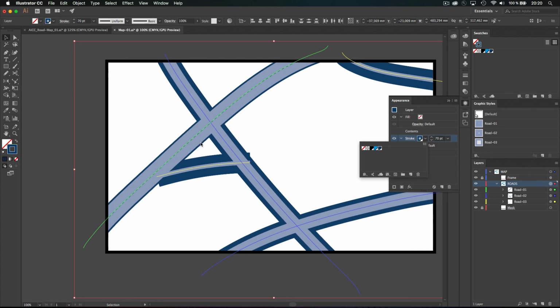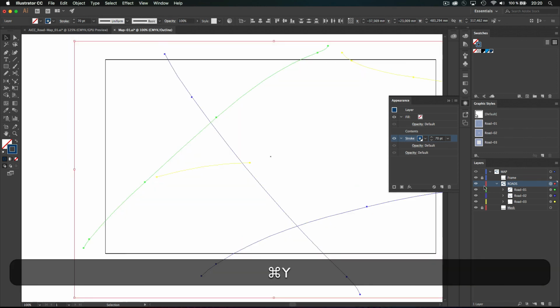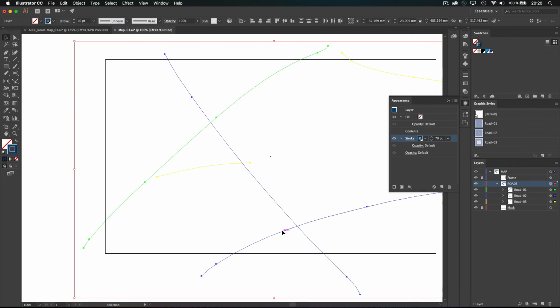And that's the tricky part, and that's where a good knowledge of Illustrator will help. Because we need to say at the parent level that what's inside, even if it's a simple path with a stroke, we need this different size stroke to be considered at the parent level as a shape, as a fill and not a stroke, to be precise.